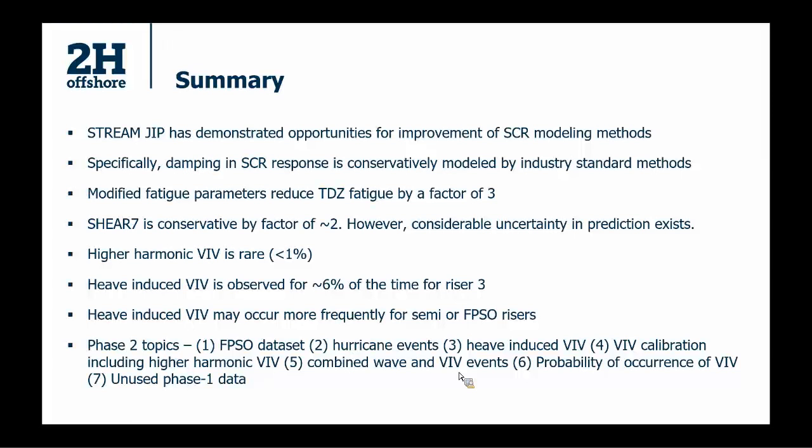First question was, did you do any study on the seabed effects on the riser response? Yeah, that's a good question. Seabed effects is another layer of uncertainty, and for this phase, at least, we try to stay clear of it. Because we need the instrumentation. We need enough strain loggers at the bottom, placed closely to really study the effect of soil. So whenever I say touchdown zone loggers, I'm talking about a logger that is about 100 feet from the nominal touchdown, so that we are steering clear of seabed effects.